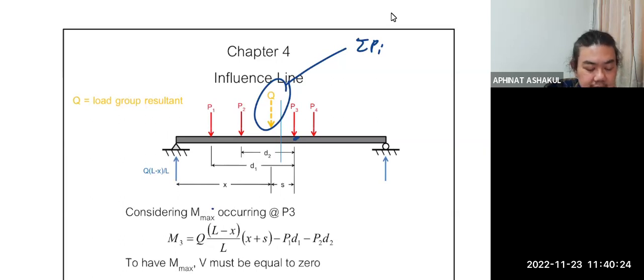One thing that has amazed me in not a very good way in the past years is that people wonder where the maximum moment occurs even after they know how to place the loads. Whatever happens, think about the shear force and bending moment diagram. When you have the maximum moment, what is going to be your shear? 0. So maximum moment always occurs where the shear becomes 0.